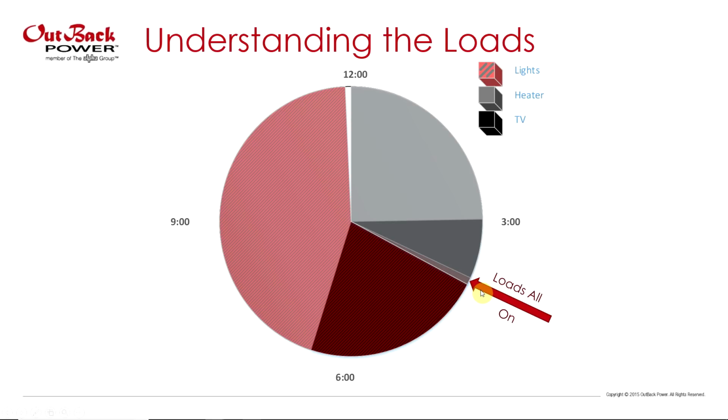Okay, so talking to the end user, we do know that there is an overlap when all of the loads will be on at the same time. So we know that that's going to be our worst case scenario. And then also, we know that the batteries will be discharged over 12 hours a day. For whatever reason, the end users are using 0 loads between 12 a.m. to 12 p.m. So in the mornings, they're not using any loads. That will come in handy when we size the batteries.